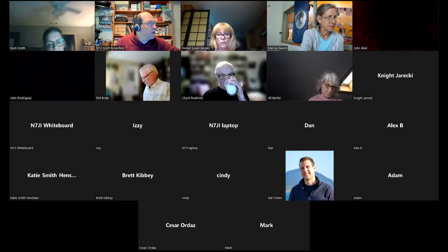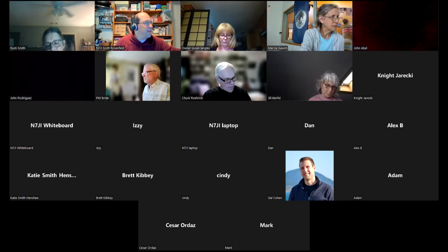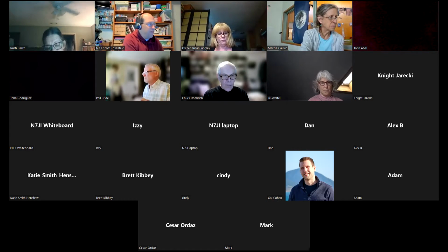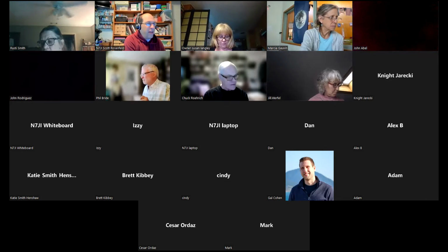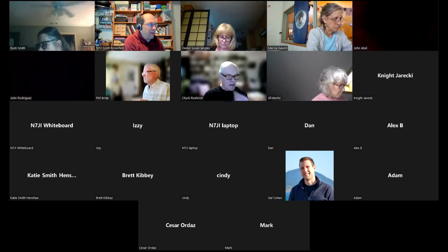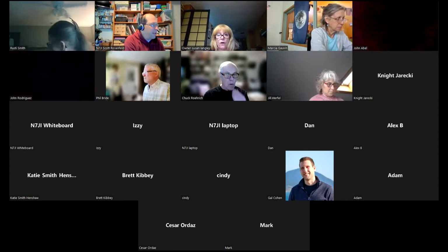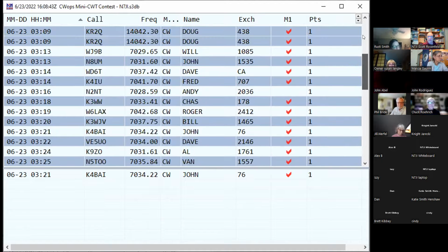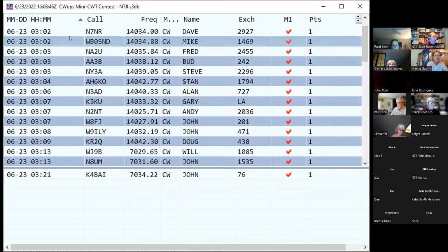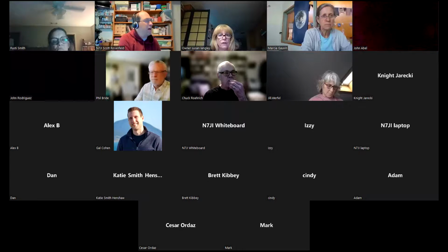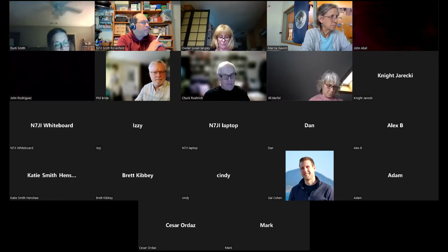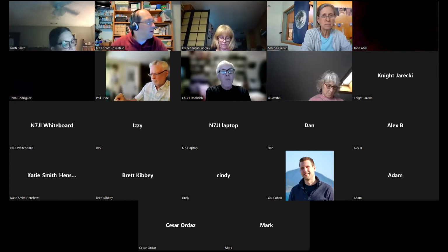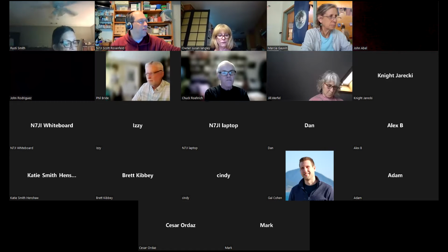How can a computer be used as part of an amateur radio station? For logging contacts. Just for fun last night, I did some of that. There was a contest going on that I participated in, and my log looked just like this. So this was 1 hour of operation, and I used my computer to do the logging. It's also used for sending and receiving Morse code, and for generating and decoding of digital signals.